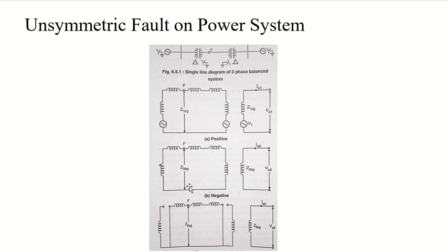So this Thevenin's voltage source is the pre-fault voltage at my fault point, and this equivalent impedance Z1 EG is the impedance seen from my fault point again. Now, the positive sequence impedance of my synchronous generator, which we discussed in the previous lecture, depends on the state of my machine, and we know there are three states.